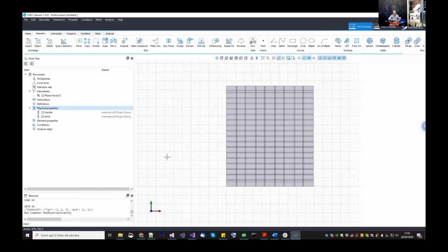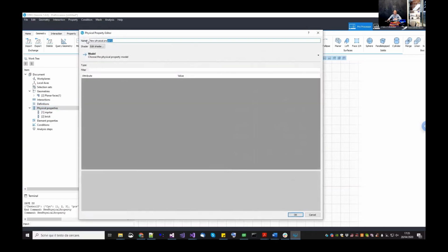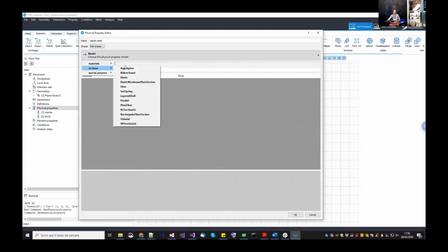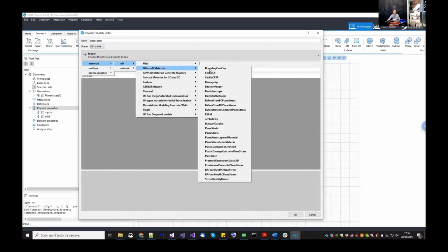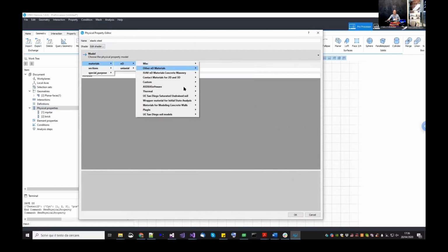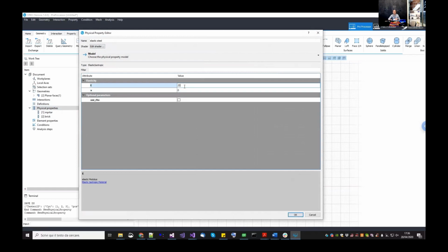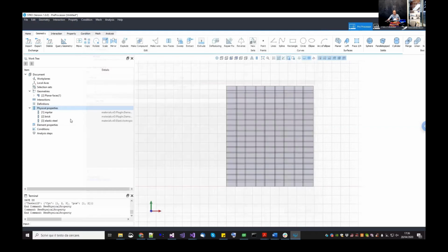We just need one extra material model, which is steel. Steel will be elastic for these 2 layers of rigid beams. So we create an elastic steel material, ND, other ND, and elastic isotropic. Maybe we have 200,000. Hope it is fine. I don't see from here. Yes, 0.3. Okay, for the steel. Now, these ones are 3-dimensional materials.